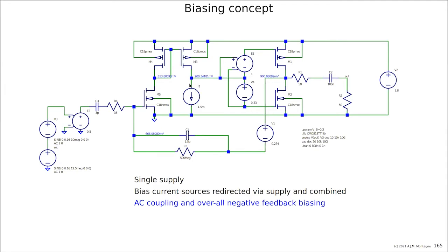Because if you want to know what the noise budget for I1 is, you just add a noise source here and transform it to equivalent input and see what the noise contribution is. But you can also say, if this is a unity gain current amplifier, then I might as well place this noise source just here.